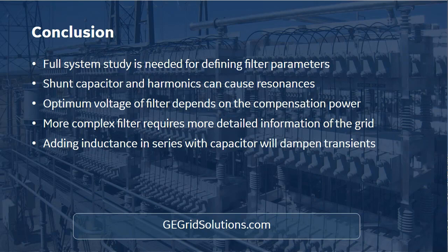So it's not really trial and error, and not really guessing. We will have some information, and then we will make a high number of simulations with different network impedances, and by that we define the worst case to be used.